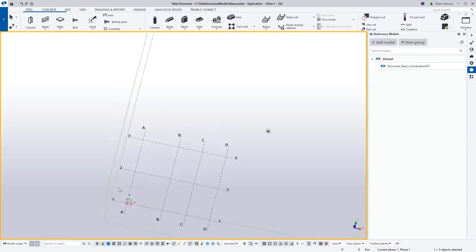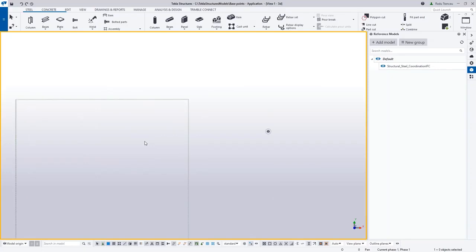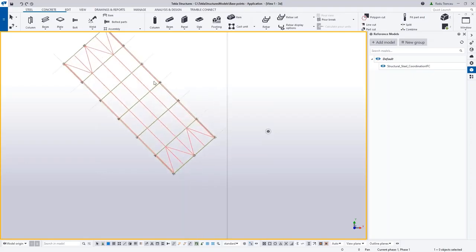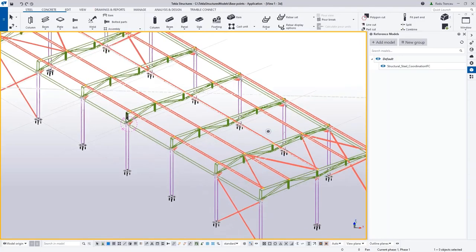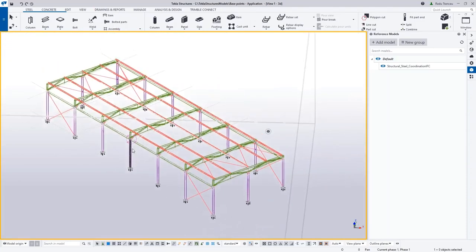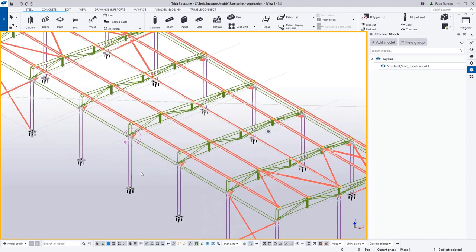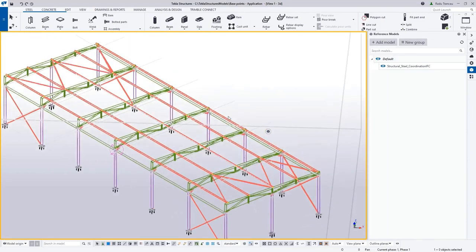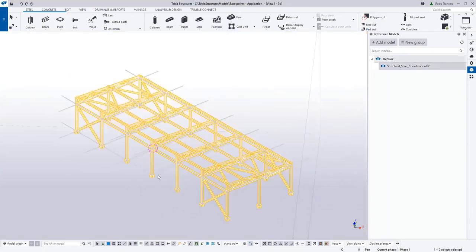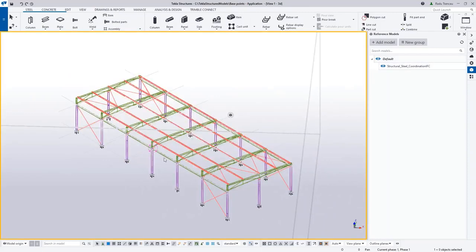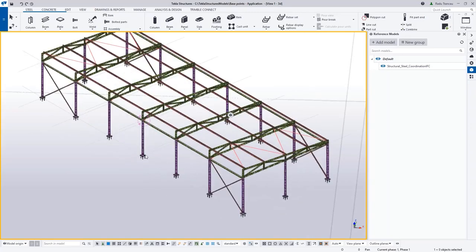So instead of just doing this model here and starting the modeling, you will need to import that model next to Tekla's origin. That is a very, very common mistake that I've seen getting asked through support, and I will quickly demonstrate what happens if you start modeling at this distance. So let's say the majority of people will just start modeling over this IFC straight away.